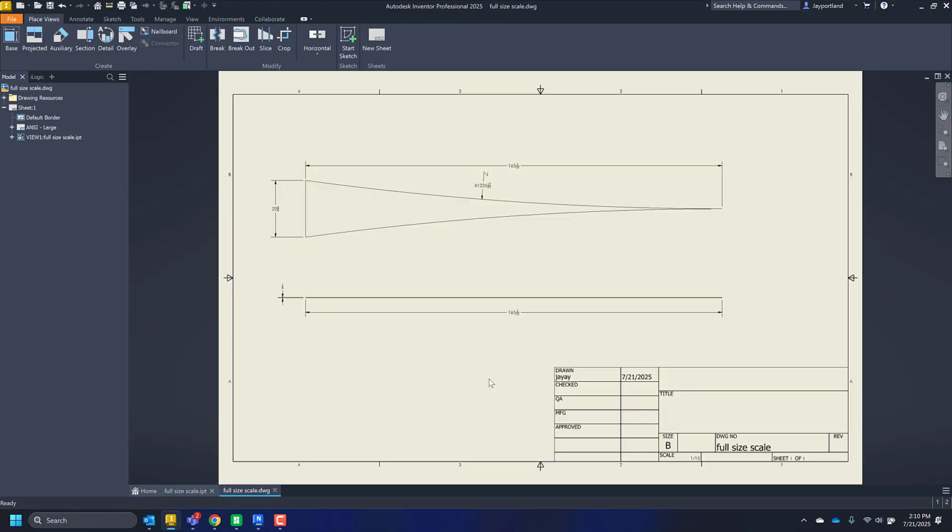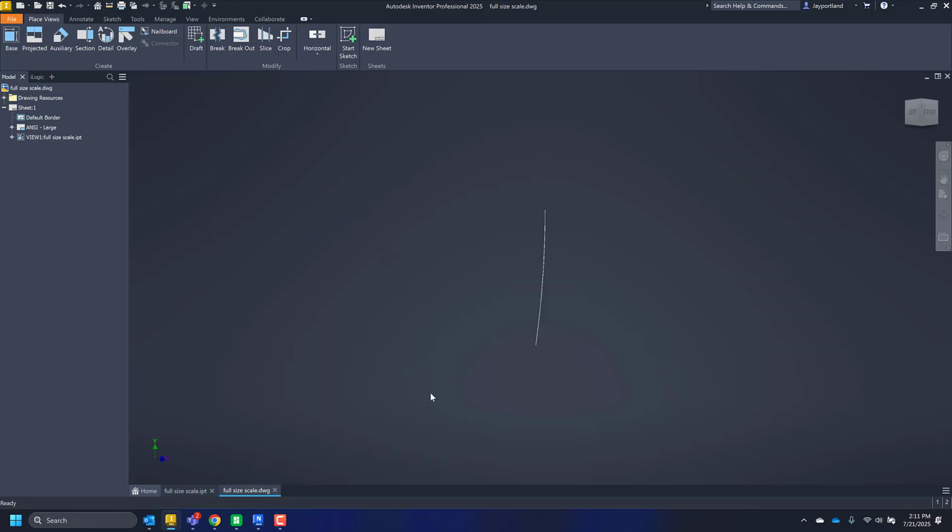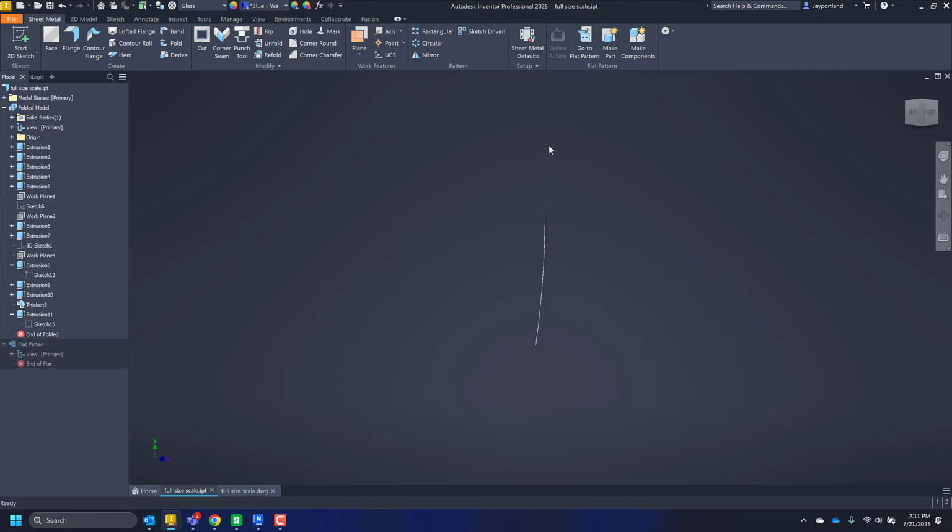Anyway, I fully dimensioned all the stuff, including the radius, which is kind of ridiculously large. That's 1,225 and 17/32 of an inch. It is a ridiculous radius here, but it's fine. We need to have that curvature there, and that's what the numbers work out to be according to the model. And of course, you can see that I placed the flattened portion of that wedge here. This is the curved portion, and then I've got the flattened geometry.